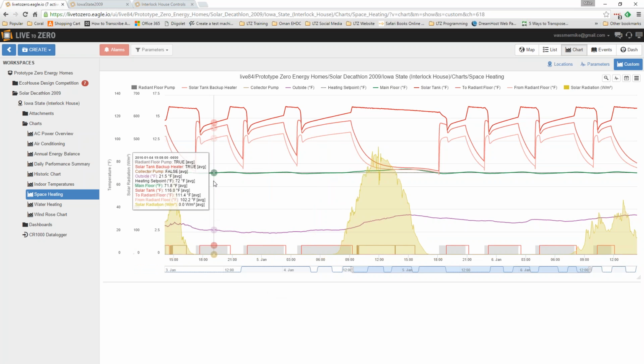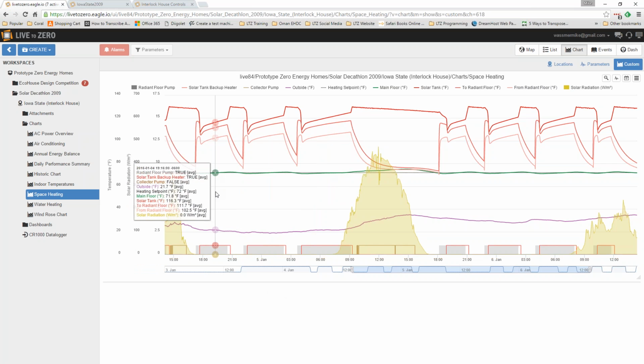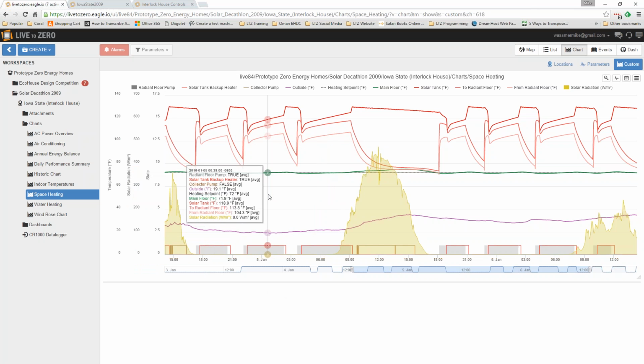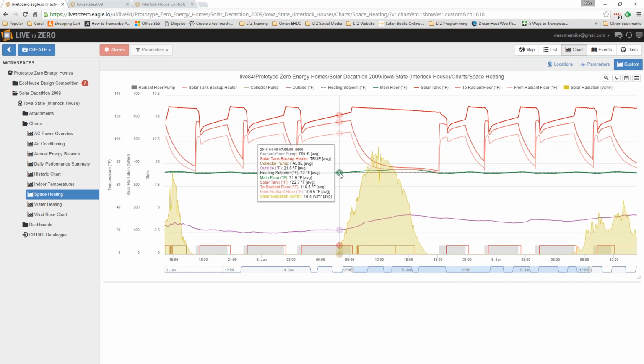So what was happening is that if I turned the temperature down to, let's say, 62 or even 64 at night to save energy, in the middle of the winter it takes many hours for the house to heat up again, so that it's back to 72 by the time they show up in the morning. The reason for that is because this is a high mass system. When you turn on a furnace with forced air heat, the building heats up very quickly.